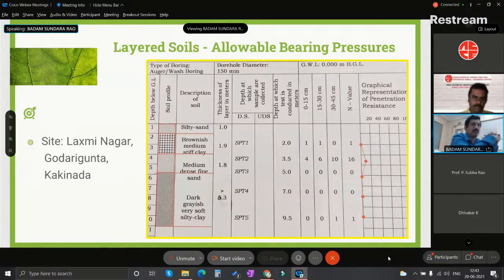Again, under the 6 tons per square meter of loading, that is the bearing pressure we are applying on the foundation soils, we have to check what settlement is expected after the completion of the structure, during the design of the structure. That is of course important. In most of the cases, we found that this SBP value, that is, the settlement criterion, once we look into the code, the permissible value for an RCC building with isolated footing resting on clay is a maximum of 75 mm, and for a raft, it is 100 mm. Even 75 mm is a higher value, but taking directly from the code, we take 75 mm.